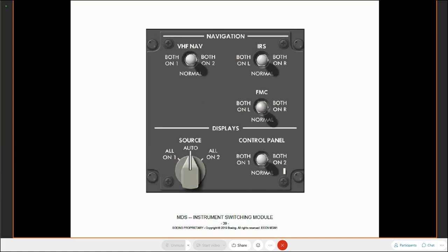When I do that, it connects the first officer's EFIS control panel to the captain's side. So when the first officer makes changes on their EFIS control panel, it will not only change the information shown on the first officer's side, but it will also change the information that's shown on the captain's side. Okay, again, allowing us that flexibility if I lost one of my EFIS control panels.